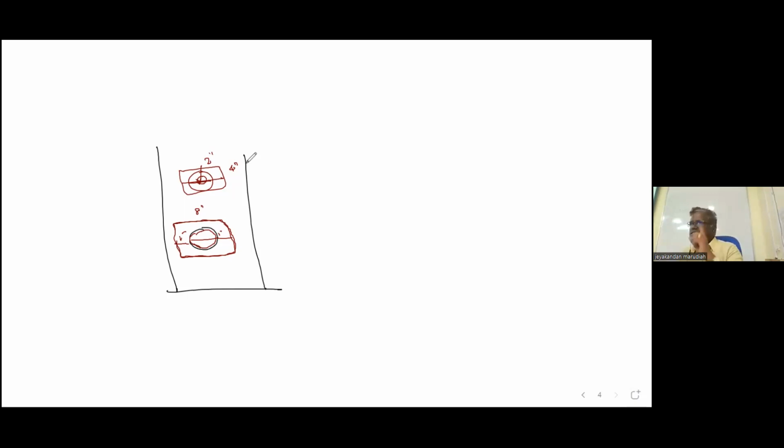What is the joint efficiency? There is one more thing. Remember, in patch plate welding, when welding on both sides, it is fillet welding. Fillet weld on both sides, E we will take 0.7. Fillet weld on one side only, we will take 0.35. Now what efficiency will we take for this?